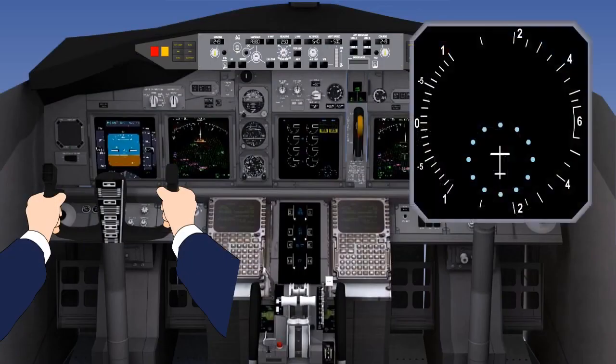On receipt of a traffic advisory, crew should try to locate the target aeroplane and be prepared to respond to a resolution advisory if the situation changes. If the aircraft cannot be located and gives further cause for concern, then crew should seek advice from air traffic control.